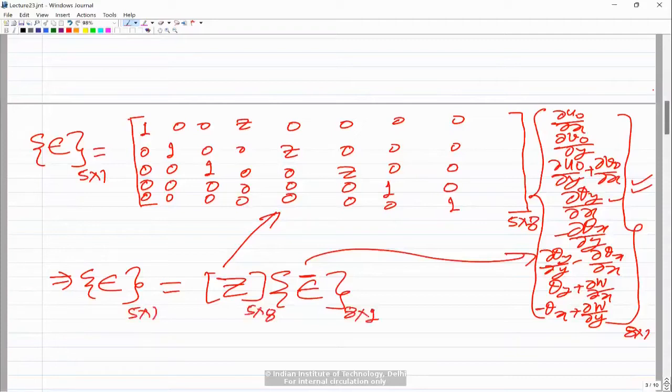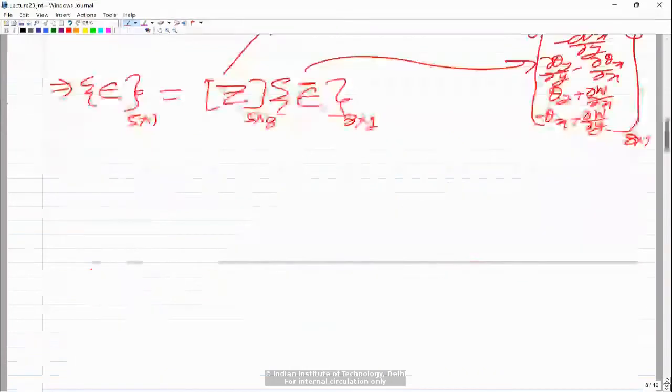So this is as far as the strains are concerned. It is similar to other problems. Only thing is we have more number of strain components, and out of those epsilon xx, epsilon yy, and gamma xy are basically linear functions of z coordinate.